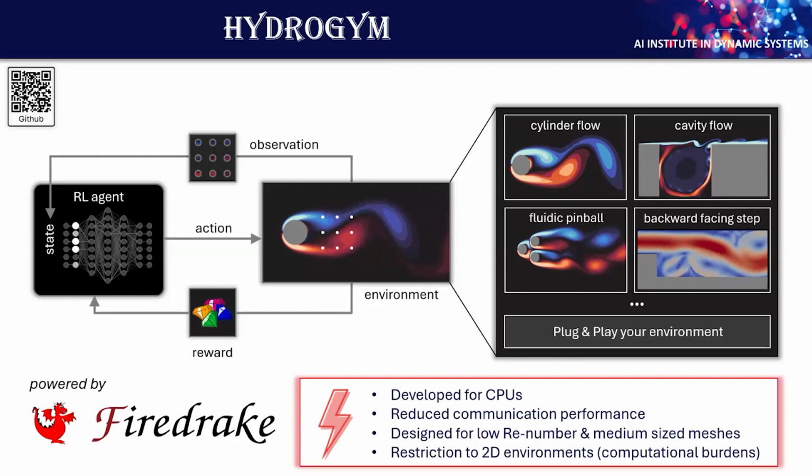However, we quickly noticed that Firedrake also has some severe downsides for our project, since it is exclusively leveraging CPUs. And there are currently no efforts in porting that to GPUs. And therefore, you basically can say Firedrake is mostly intended for small and medium-sized PDE problems. So as a result, we've been mostly limited to 2D environments, which already required a significant amount of training effort. For example, for larger problems, it was on the order of 2 to 3 weeks. So it was quite obvious for us that we need a more efficient CFD solver as a backbone for our RL setup, which in the end also allows us to leverage more modern hardware accelerators like GPUs.